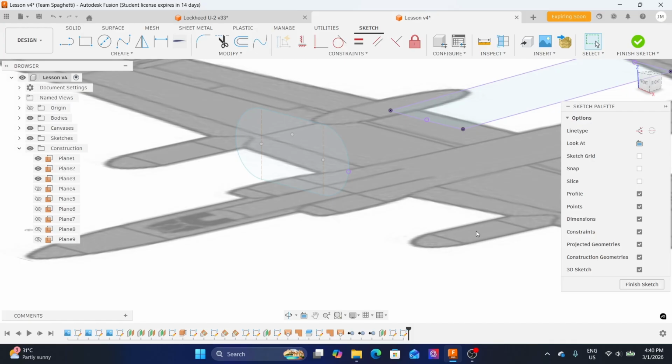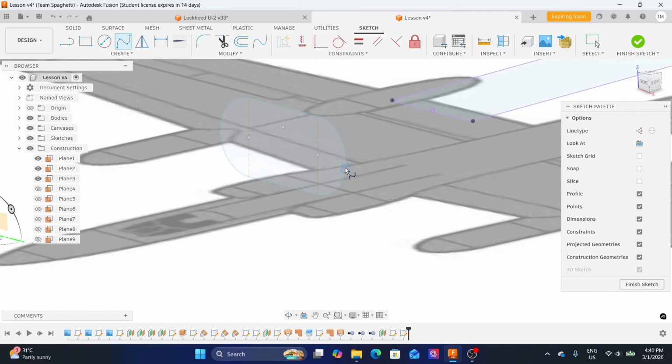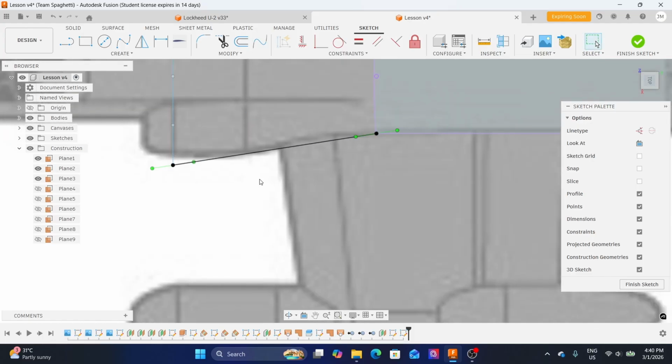and now we could proceed on creating using the fit point spline. So here, our first point would be this point here, 1 and then 2. Hit the check on your keyboard once done, and hit escape to exit the tool. And then let us switch to the top view, and then same as before, we're putting 2 constraints here at these tangent handles right here.